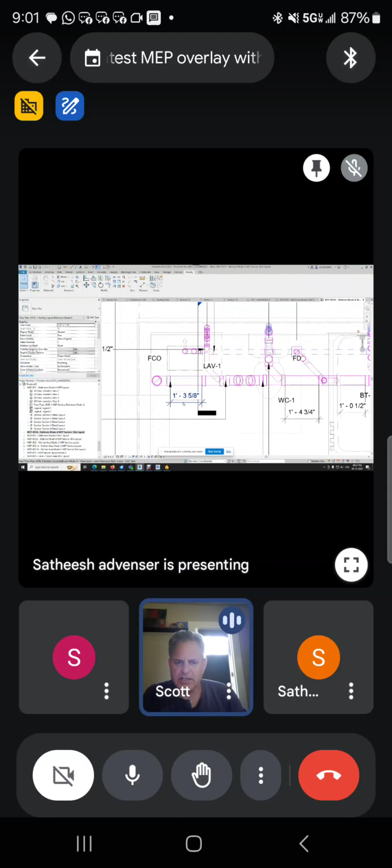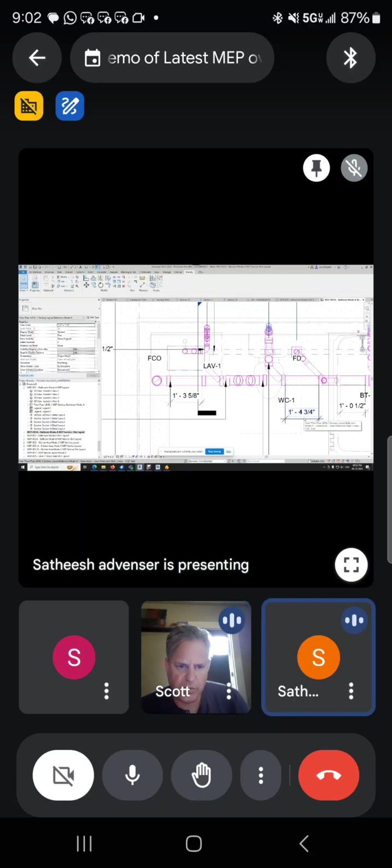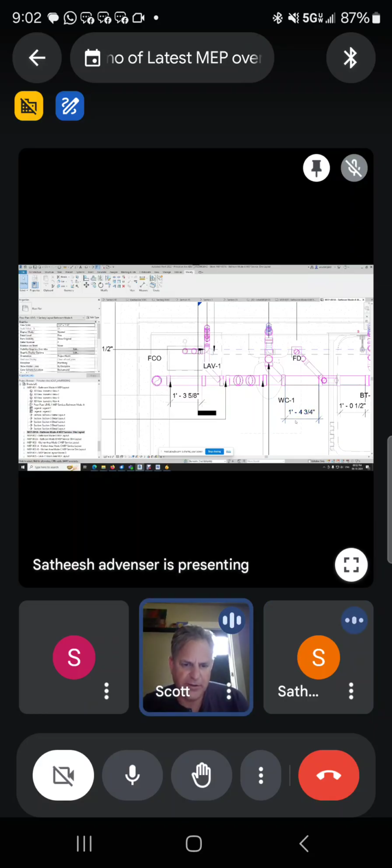I see exactly the measurements, but here's where I was kind of hoping for. In reality, though, what you measured, that 1 foot 3 5/8, which is perfect. That person then could add a 1/2 inch to an inch on that measurement, and that's the piece he's going to cut, because it's got a flange that slips into there. So really, when you slip that 1 foot 3 5/8 part into there, what is that part measurement?